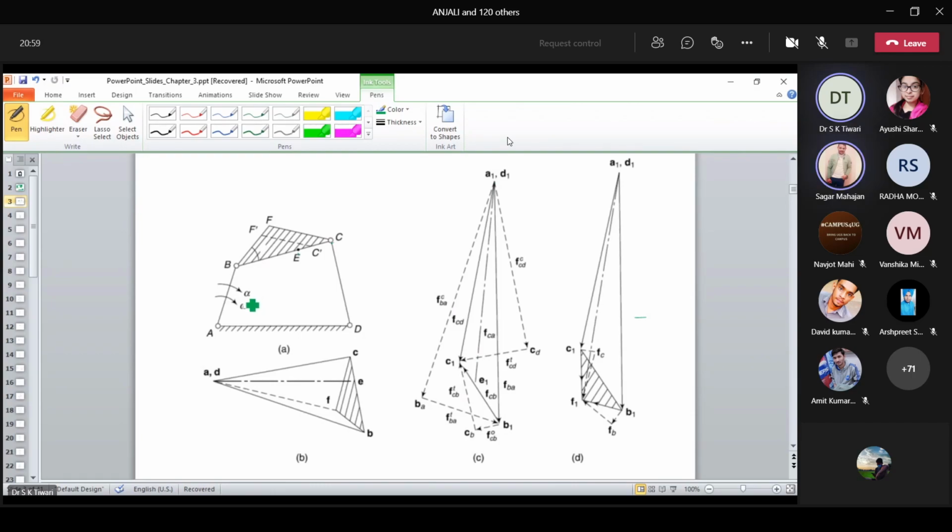Yes, sir. तो मैं सबसे पहले लिखूंगा, I will find out FCBA, centripetal component or the radial component of acceleration of point B with respect to A, because for B, A is the center of rotation right now. आपको मालूम है सेंट्रीपिटल के लिए मैंने क्या लिखा था? FC is nothing but V square by R. तो वही फॉर्मूला मैं यहाँ यूज करूंगा, velocity of B with respect to A square divided by the length AB. Okay.